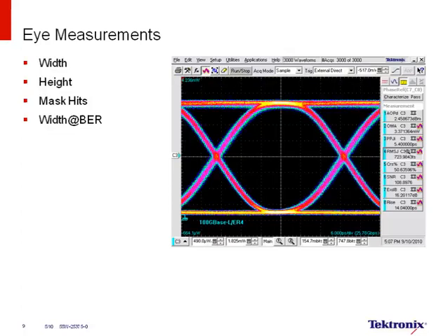Without fail, while looking at eye diagram measurements, one of the biggest issues I've seen is that folks are not setting up some of these settings to be able to recover and create the eye diagram. And what you have is either an eye that's open when it shouldn't be, or a closed eye when it should be open if you don't have the right loop bandwidth or PLL order.